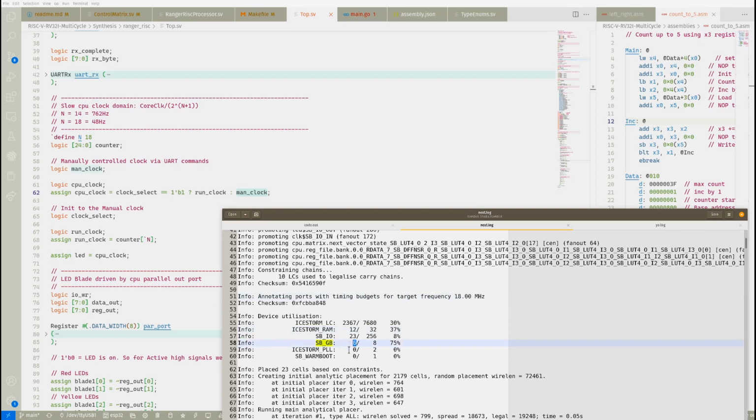Now these buffers are high drive, low skew, and the key here is low skew, because you ultimately want all of your components as close as you can to the same clock domain. If there's a significant amount of skew, technically any kind of skew, you've entered into a new clock domain. But for our purposes, at a lower frequency, that gray area between domains can overlap a bit. And in this case, it's determined that it needs 6 of these low skew buffers to distribute my clock.